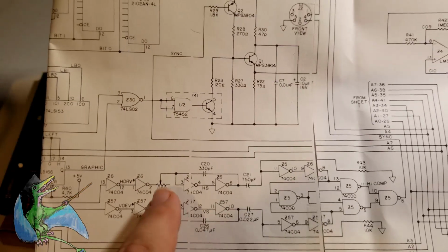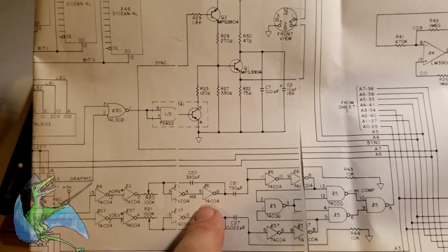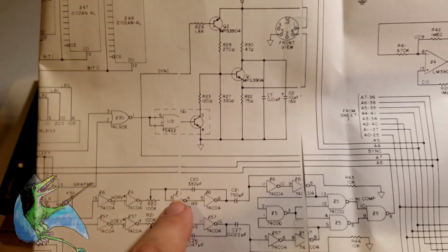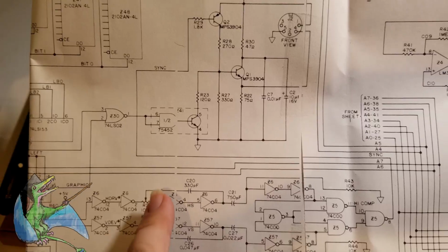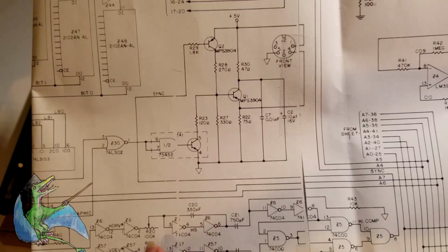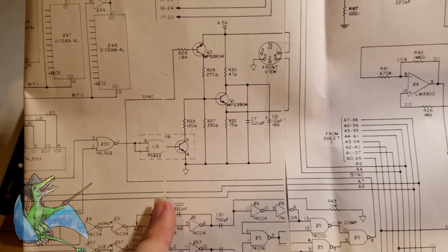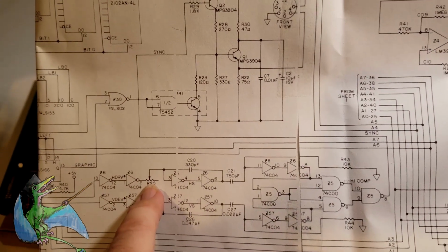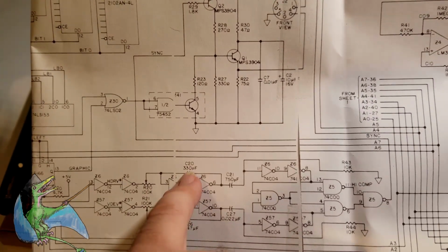Now the next step is interesting, and this is why they wanted to get it running closer to the rails. The first stage, which is achieved by a capacitor and this resistor, depends on the analog aspects of charging a capacitor up to a certain voltage. So the drive signal, when it comes in here, can be delayed by some amount, depending on how much voltage you let through this resistor, which slows down or speeds up how fast this capacitor charges.